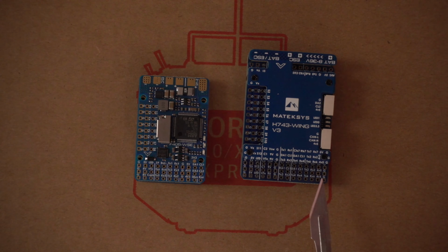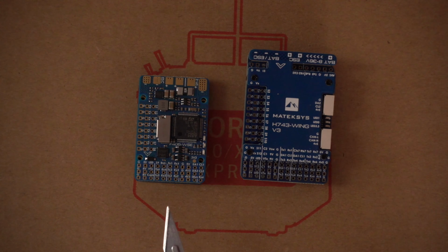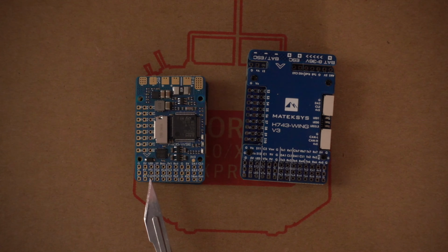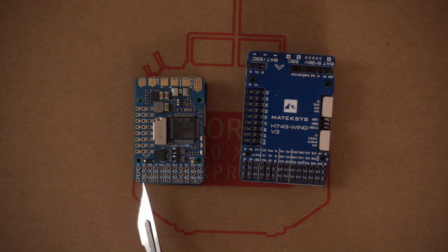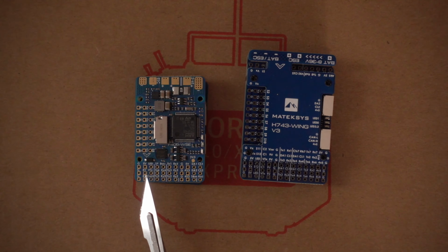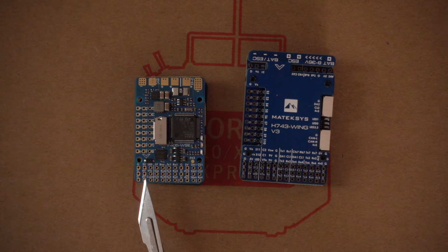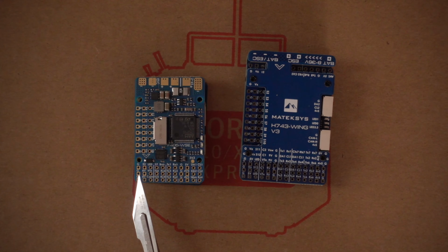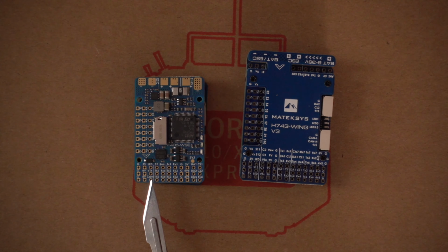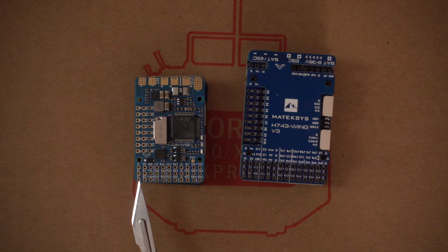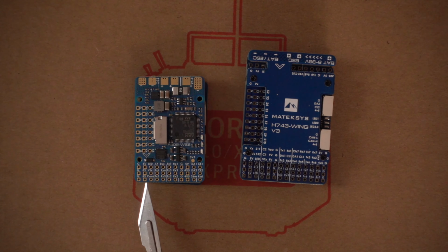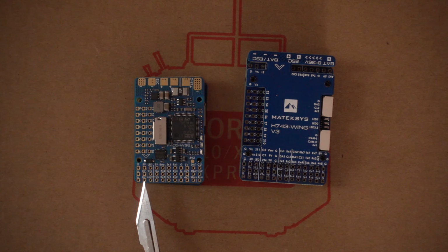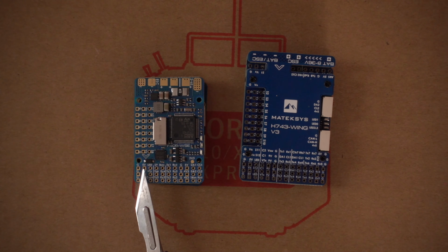So we have our receiver and our GPS module, but we need to see where we're going, so we want to connect a camera. Now on the F405, there is a cam pad. There's also this pad here, which is 8 volts. So this is a separate battery eliminator circuit, or BEC, for the VTX and the camera. So that runs at 8 volts, and then we have a ground. So the camera will plug in here, power for the camera in here, and ground here. So just make sure that your camera can take 8 volts. If not, just steal a 5 volt from somewhere and it will be fine.